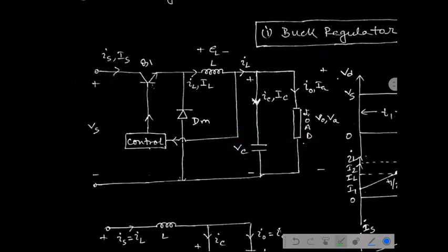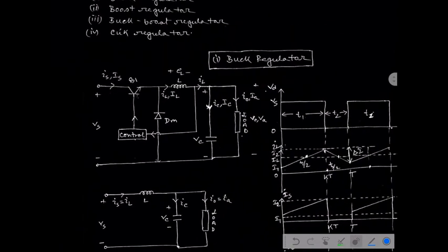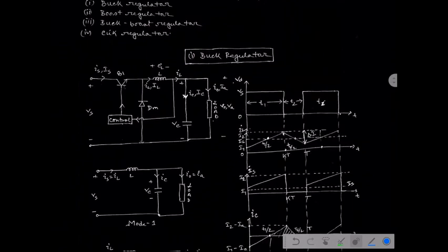When the inductor current gradually increases to the maximum value of 70 ampere, 50 ampere is delivered to the load and the remaining 20 ampere flows into the capacitor. Then the capacitor starts storing energy, or is in charging mode. This operation can be well described by the numerical example.